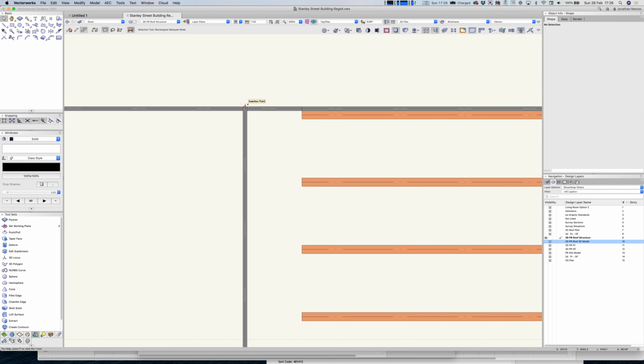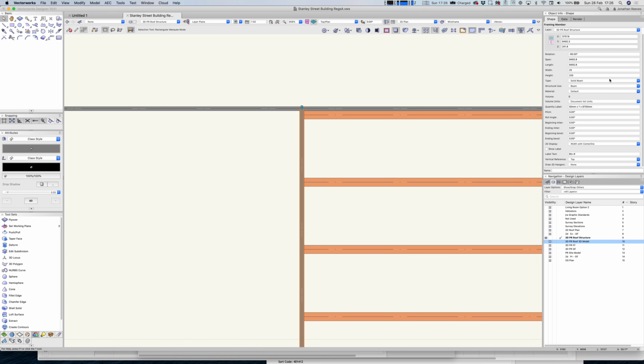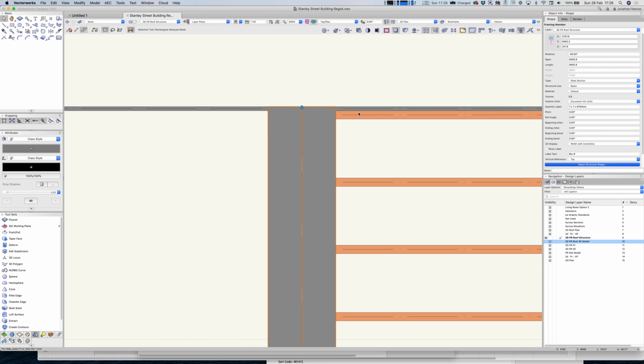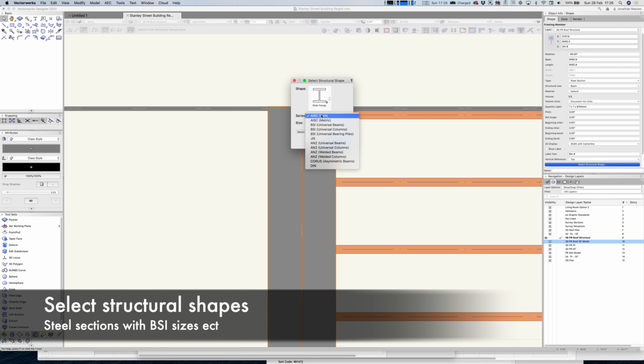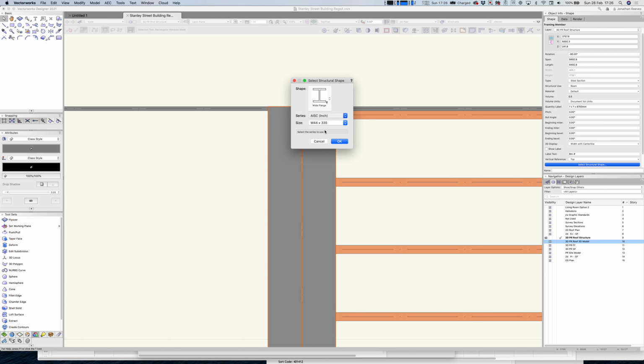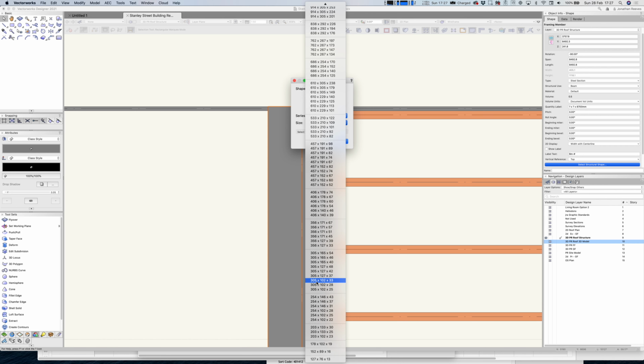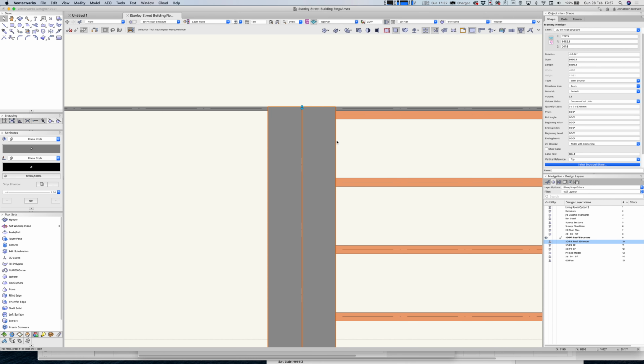As I say, we can duplicate this now. Amazingly, just turn this rafter into a steel section. So I've turned it into a steel section. I'm going to click on the select steel profile. And one thing I love about Vectorworks, it's got all the universal beam and column sizes built in already. You can put your own versions in or custom sizes, but I'm keen just to put a standard steel size in here. I'm not sure what it's going to be. I'm not the engineer. He'll hopefully give me some calculations and tell me when we get there. But I'm going to take a bit of a guess based on what I've done before with the experience. It's going to be something like a 203 times 133 times 50.